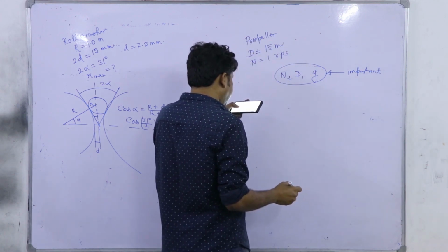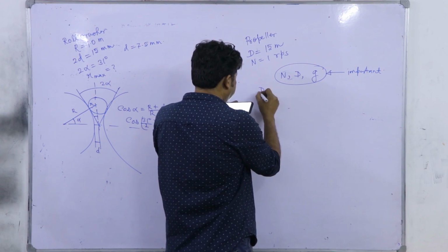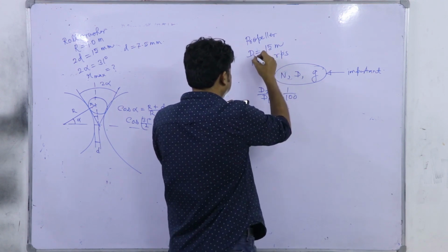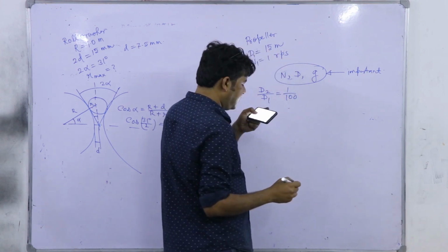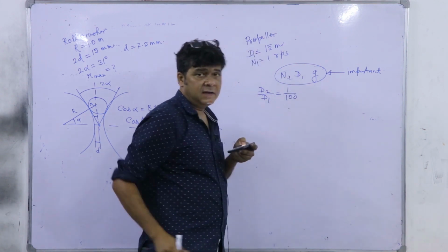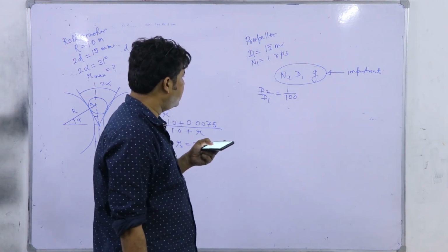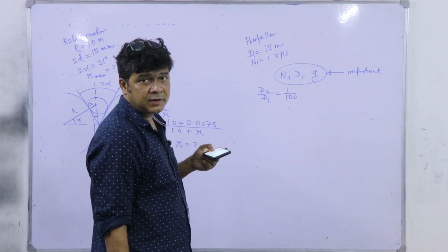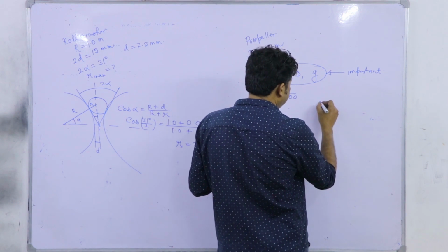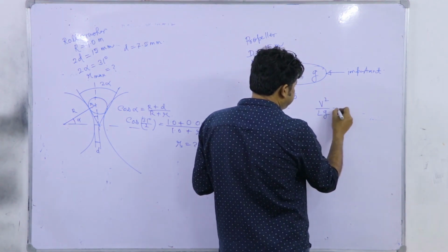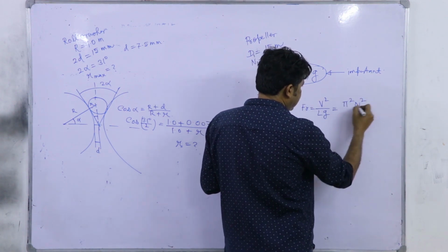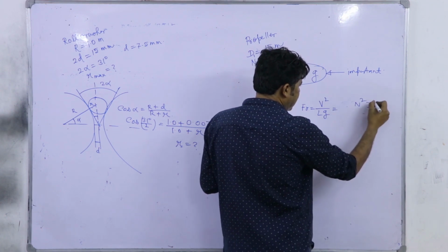The rotational speed of the lab scale model, that is d2 by d1, it is 1 by 100 scale. So, let us write these are d1. We have to calculate what is the rotational speed of the lab scale model. Here, as you can see, rotational speed, diameter and the acceleration due to gravity are important. So, we have to keep the Froude number equality, right. Froude number, that is V square by Lg. So, Froude number here is pi square n square d square divided by d into g, or basically pi square we can eliminate.